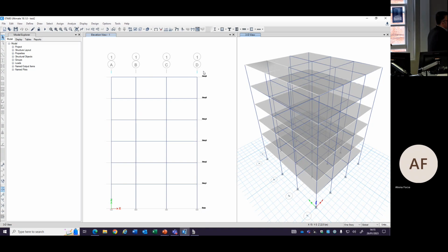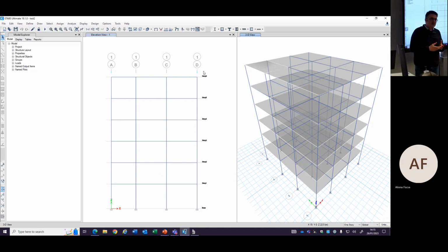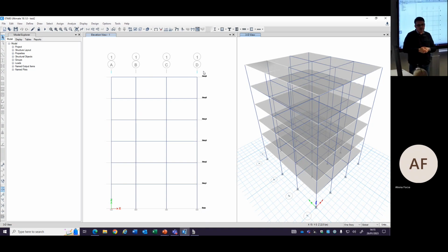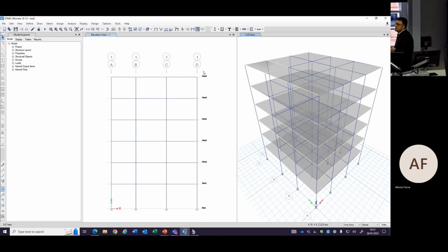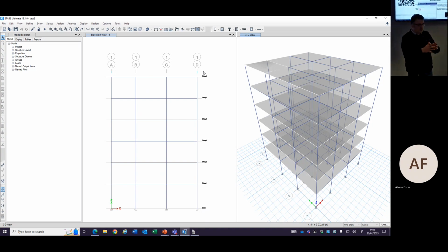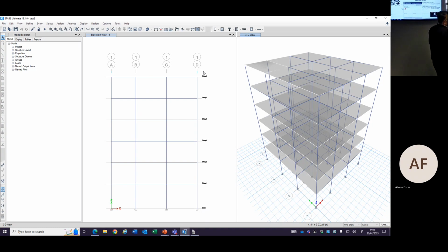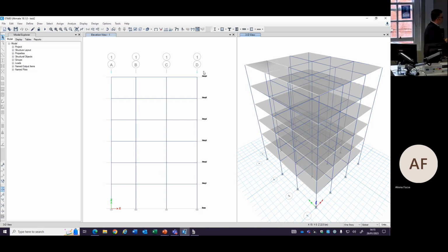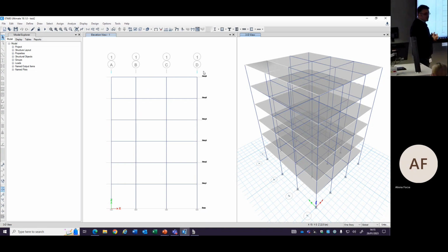For the beams, you had only the bending moment, right? You have the demand from the structural analysis and the capacity from this bending moment. You will divide those together, and you will come up with a demand to capacity ratio. If the demand to capacity ratio is less than 1, everything is okay, but if it's more than 1, you need to think of something bigger: your section, use another material, use more reinforcement. These are the strategies you can use to decrease your demand to capacity ratio.